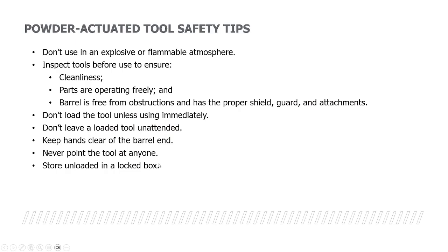Powder actuated tool safety tips. Once again, don't use it in an explosive or flammable atmosphere. Inspect the tools before each use. Cleanliness is the key with tools, folks. It doesn't matter what kind of tool you're operating. Make sure it's thoroughly clean and operating freely.